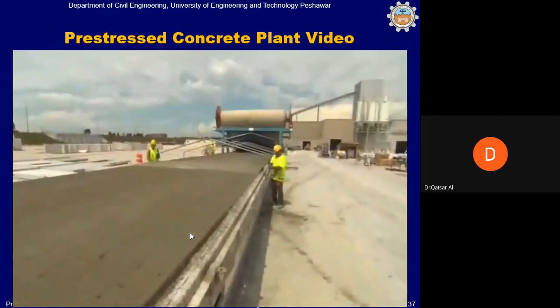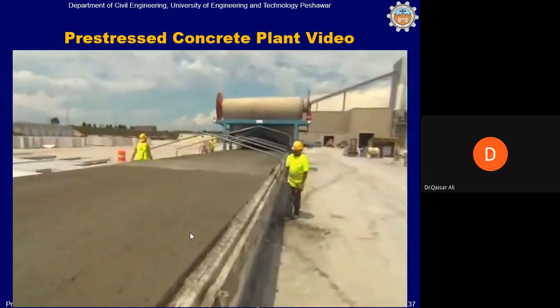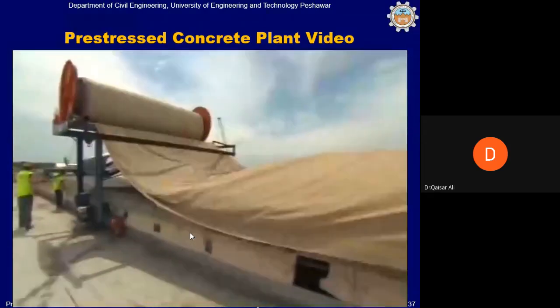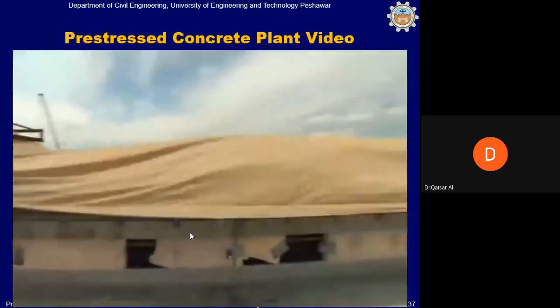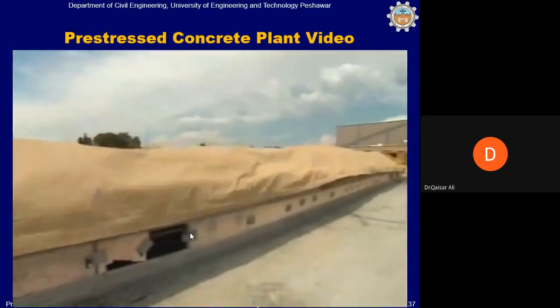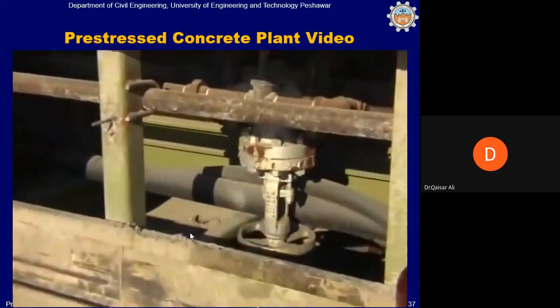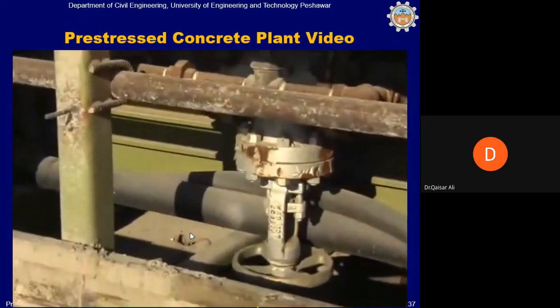The bed is now in its curing stage. Sometimes, particularly in cold climates, the double T may be covered with tarps. In other areas, they may be open. Accelerated curing is often done using live steam or radiant heat from heaters attached to the form itself.